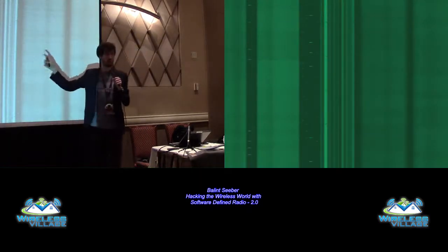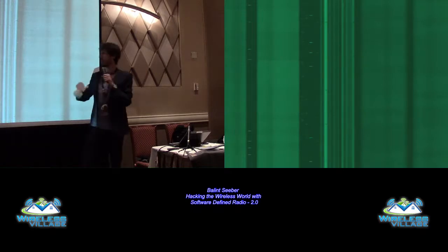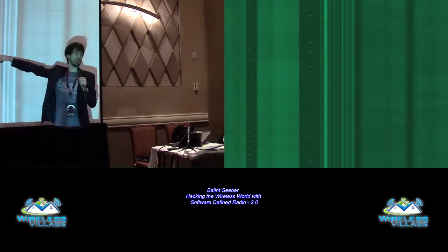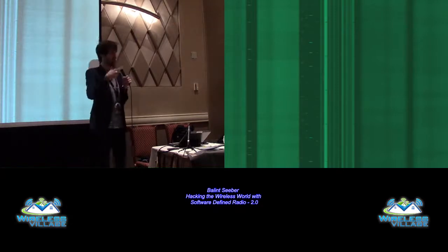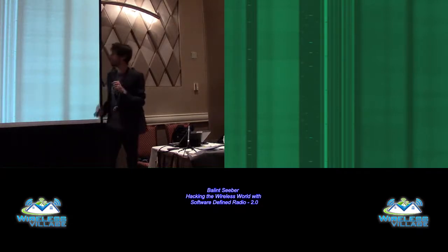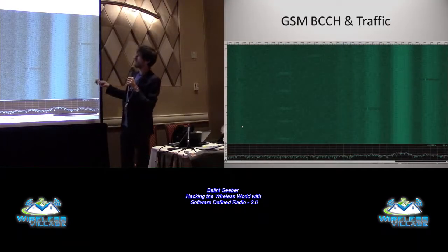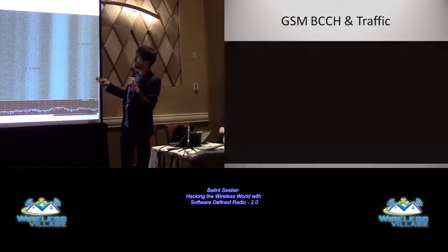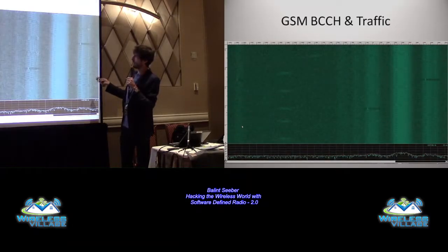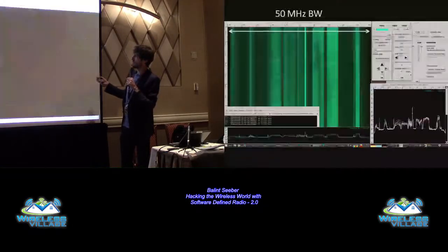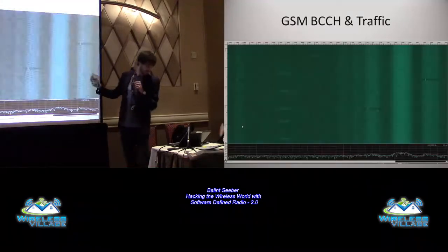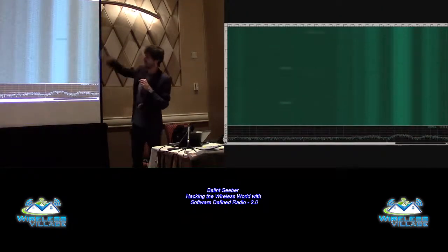And what's really cool about this program is that you can run the FFT so fast, you can see the frequency correction burst in the control channel coming down on GSM. And that's what your handset uses to synchronize its internal oscillator. And then this is actually a video of it running, I think, maybe, there we go. No, my laptop just needs a moment. There we go. So this is actually it scrolling past.